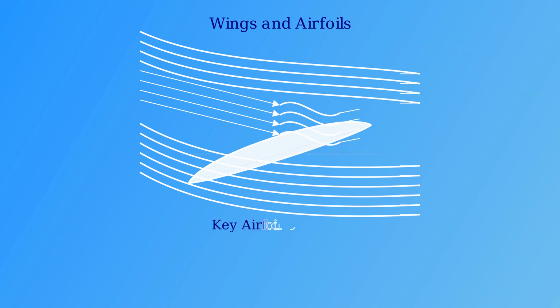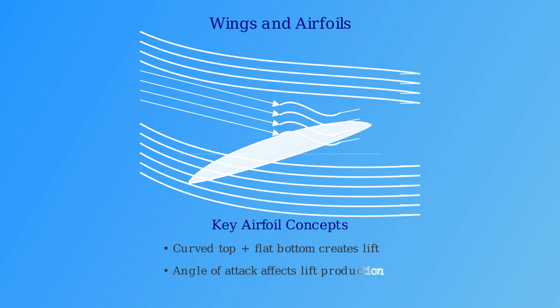To summarize, the special airfoil shape, with its curved top and flatter bottom, creates lift through pressure differences. The angle of attack is crucial for controlling lift, with greater angles generally increasing lift up to a critical point. Beyond this critical angle, the wing stalls, causing a sudden decrease in lift that can be dangerous if not properly managed.